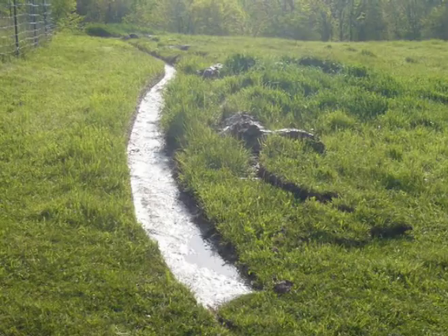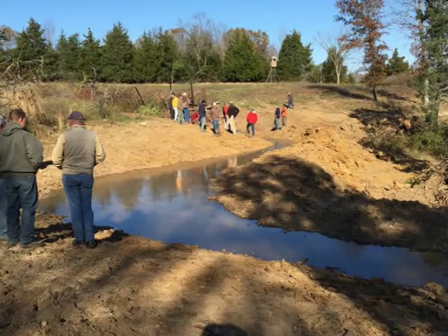The idea is instead of this water flowing away, we spread it out to the ridges. What you can also see there's a little cross piece there, and a piece there, a piece there. About every 50 feet or so, 25 feet on smaller systems, I'll just put a little check dam across. So it'll fill up one cell, overflow, fill up the next cell, overflow, fill up the next cell. Slow it down, spread it out, soak it in. That's how they operate in the rain.